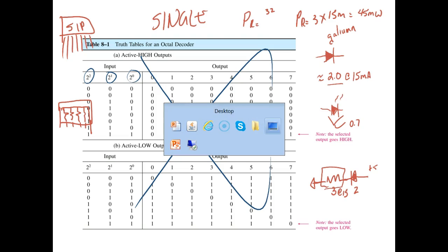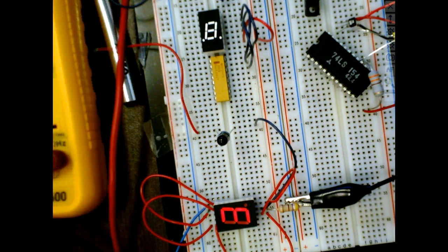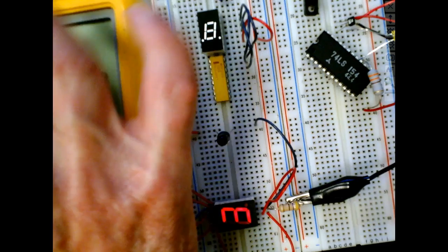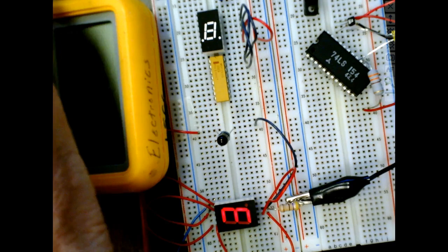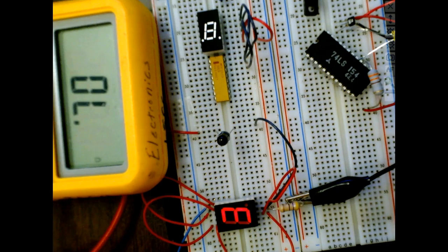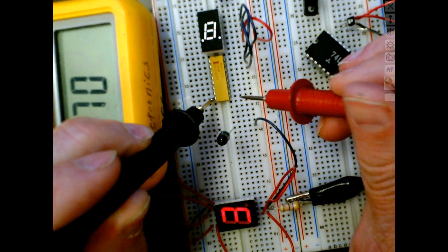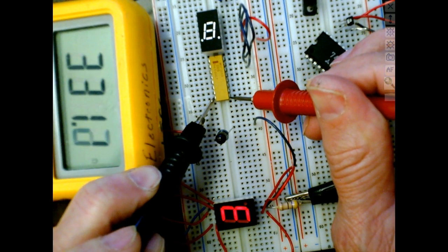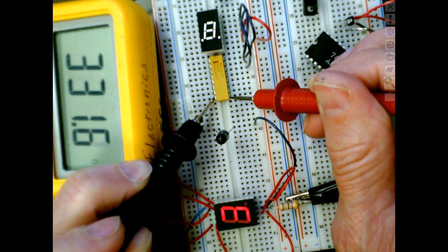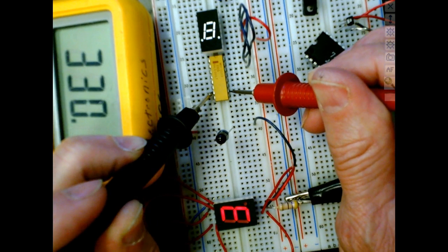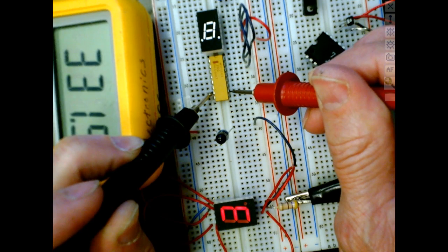So this is a 330 ohm resistor. I don't know if I can get my meter up here. I think I can lay it like this, and then I'll turn it on. Put it on the 400 ohm scale, and you see when I measure across from here to here, it measures 331 ohms. But it doesn't measure there because that's a different resistor, right? So these resistors are in here, just across each other. Does that make sense?